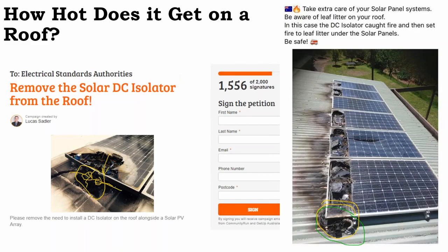Now, wherever you get a failure, wherever you get a splice or an inefficiency, and electrons are having to leap over, that's not a good, strong point within any electrical system. Down at the cell level, you get impurities on these solar cells. Electricity starts hopping across, and the cells can start to degrade along the line of the little micro crack that the electrons are jumping over. So a terminal point where the cables come in and land on a metal bar gets hotter than the rest of the box.